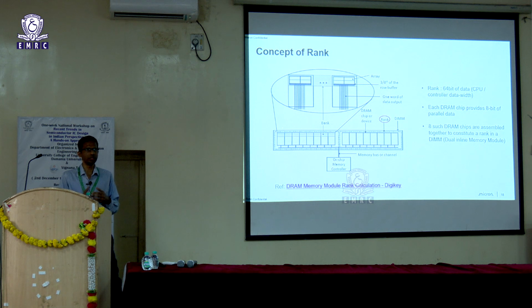Now typically we go for upgrades, 8 GB to 16 GB. We go to a center and say, I need my memory upgraded from 8 GB to 16 GB. So you add one more slot. Essentially we are creating an additional memory space, but your bus is still going to be 64-bit wide. So 8 GB is going to grow to 16 GB, but effectively whatever gets interfaced with your CPU is still 64-bit.